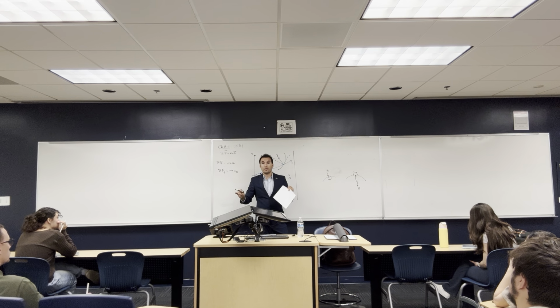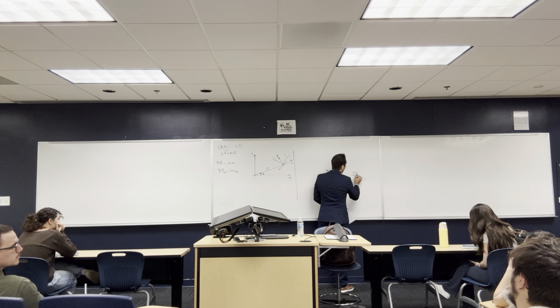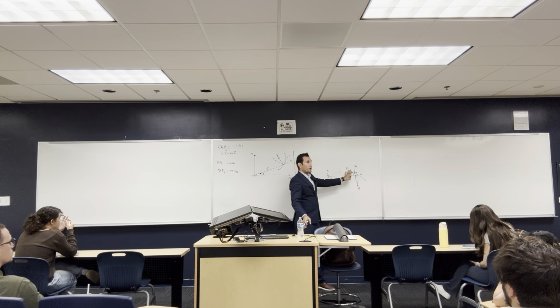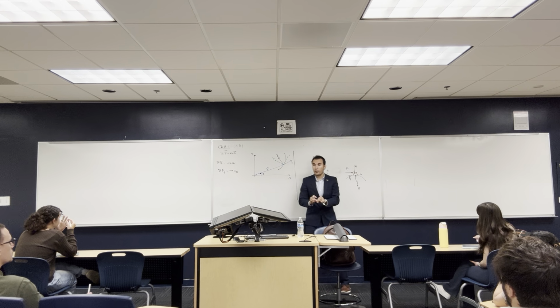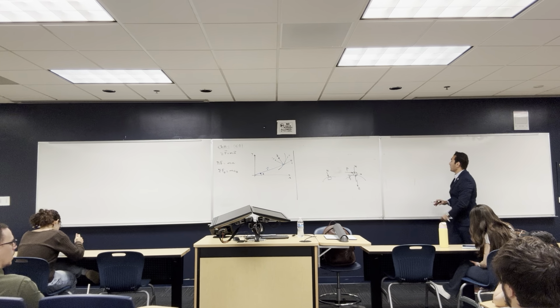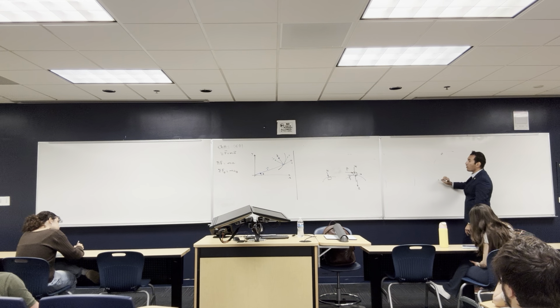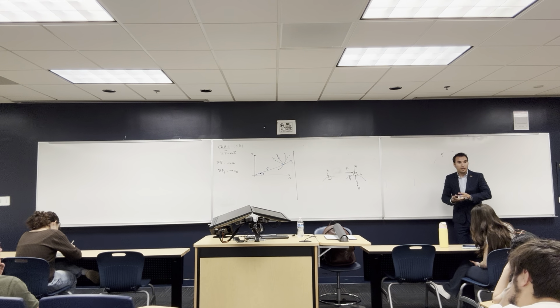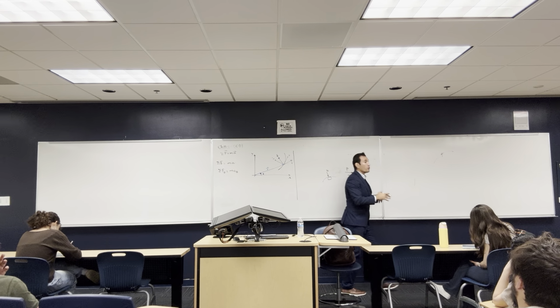That's basics that you should know: how to map the forces on a body. Let's say this body is moving that way. That's the tangent direction. I know that there's a friction that way, and I know that there is weight going down. And if there is a pushing force, this pushing force P is going to be that way. When I give you a problem, I'm not going to put these forces for you. You have to understand the problem and try to map these forces. Like I told you, if a car is moving on a curve, the weight is going down, and there's a friction, and there's the normal force. You have to map all these forces by yourself.